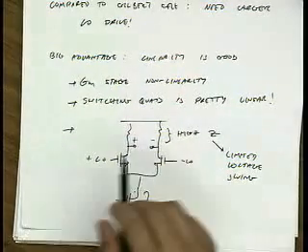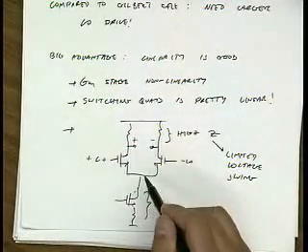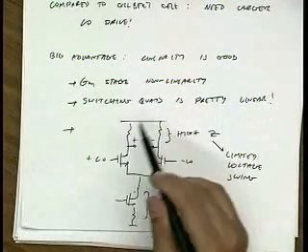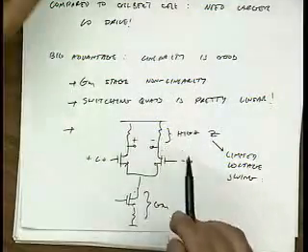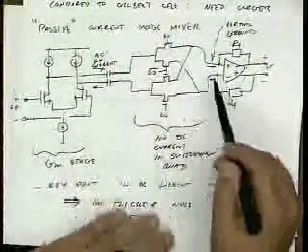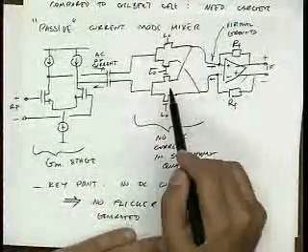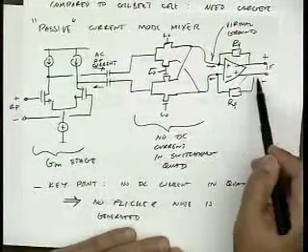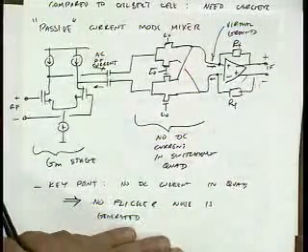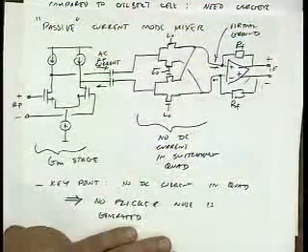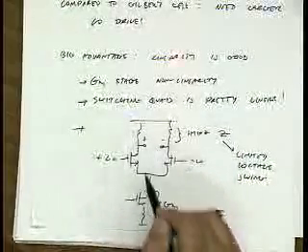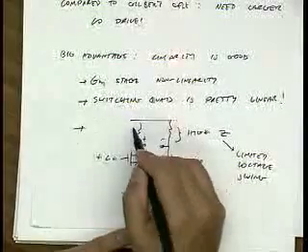So if I'm designing this mixer, I either have to limit the DC current or I have to limit the size of this resistor. But at the end of the day, I'm restricted by how much current I can actually swing because of the voltage. Over here, I don't have a similar limitation because I can swing a large current here, and since it's a low impedance node, there's no voltage generated. I only have to worry about voltage swing at the output of this stage. Okay, so it decouples the problem. So here I have the full supply voltage available to me, whereas in this case I only have a limited supply voltage available to me because of the headroom taken up by these devices.